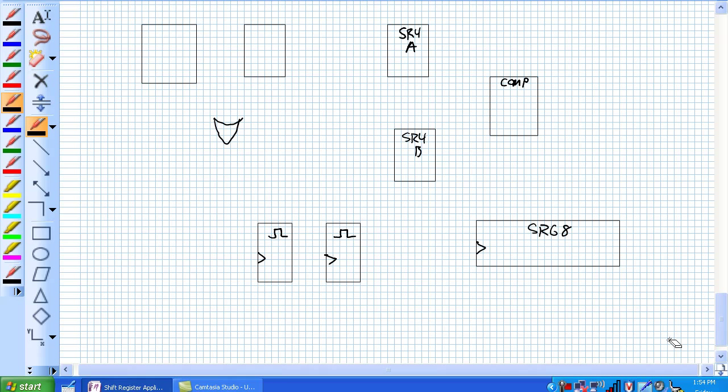Okay, here's our security system. The key to this whole thing is this magnitude comparator and its connection to this shift register at the very end. That's the output shift register. It's basically this shift load command here. And by the way, that's the equal input there. Anytime there's an equal, there's a 1 there, and this thing shifts 1 to the right.